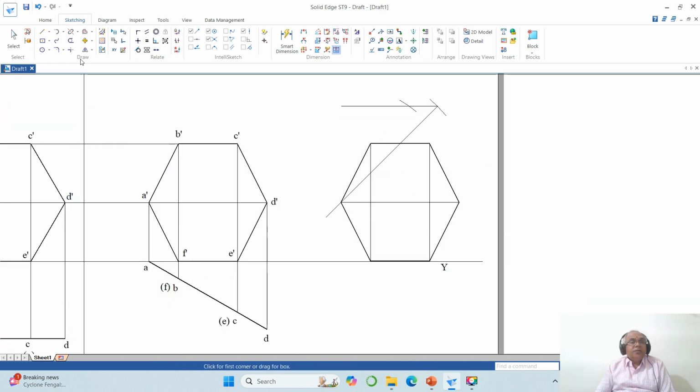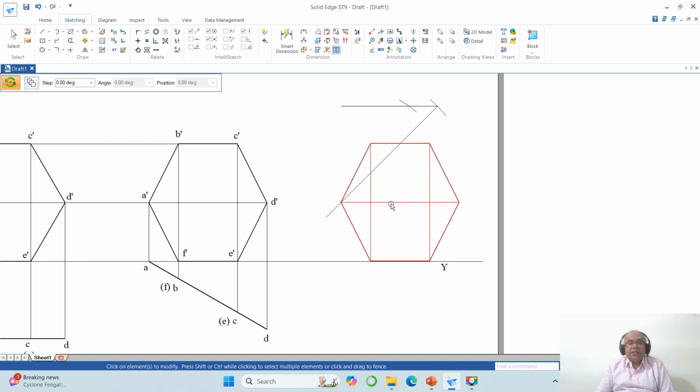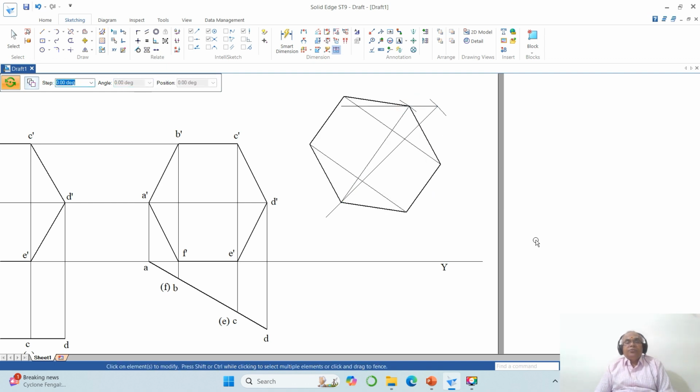Okay. Then go to rotate command, disable copy. Yes, you select this, and you take this endpoint. With this endpoint as reference, you take it onto this intersection line. So now once you place it, now what happens? Accordingly, we need to name them. So how to do that? So go to move, enable copy, you take that A dash and keep it here.